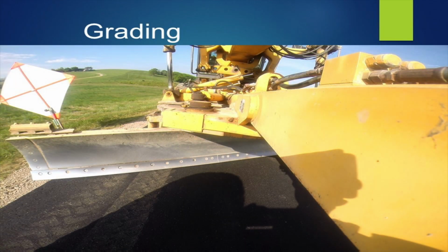Grading, if you will, that is your ride. On a lot of applications, since you can use a variety of surfaces, you can use a surface treatment, you can use a very thin layer of asphalt, and obviously, if the grader operator is having a bad day, you're going to get a bad ride. So that is absolutely critical to have that operator trained properly, and able to deliver the rideability that the department is looking for.